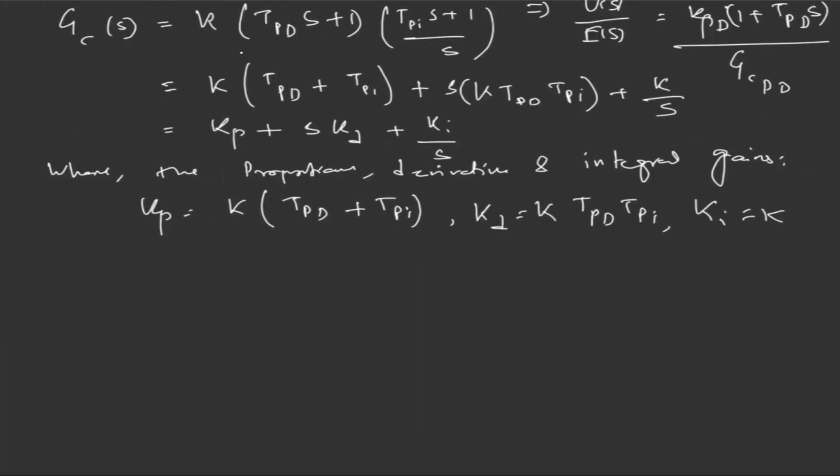Now we'll find how we can design the PID controller in frequency domain. We'll start by first looking at the overshoot and phase margin and how they are related.